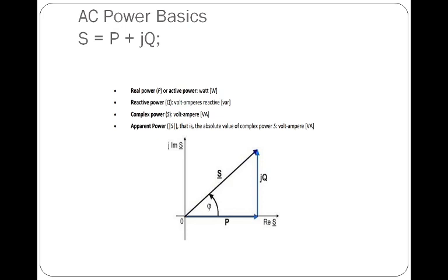We care about apparent power because even though the current associated with reactive power does not do useful work at the load, it eats up the cable or wires, as the case may be, and this wastes energy. So conductors, transformers and generators must be sized to carry the total current, not just the current that does the useful work.